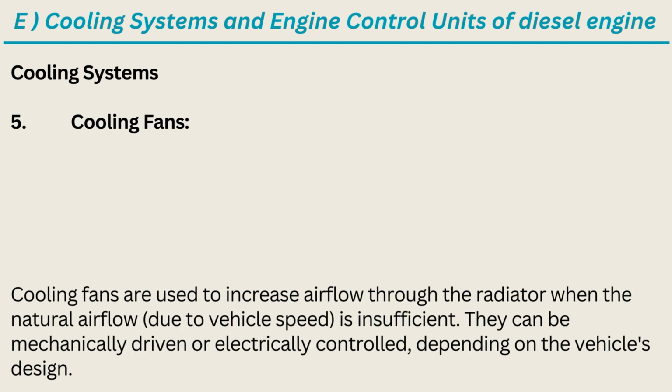5. Cooling fans. Cooling fans are used to increase airflow through the radiator when the natural airflow, due to vehicle speed, is insufficient. They can be mechanically driven or electrically controlled, depending on the vehicle's design.